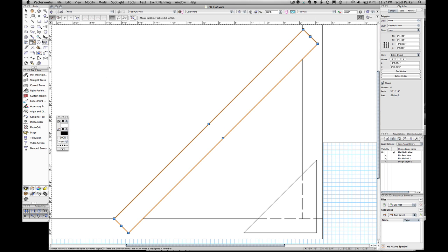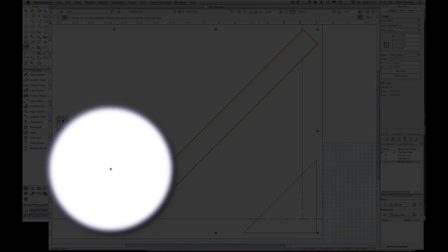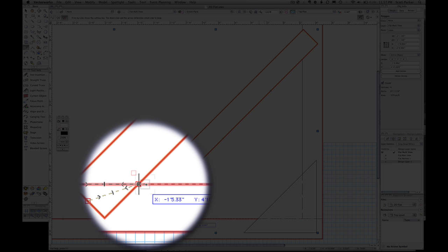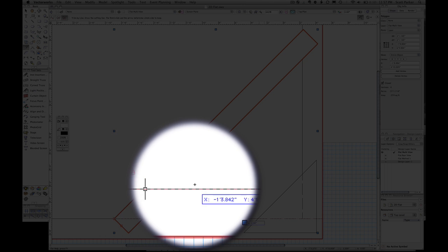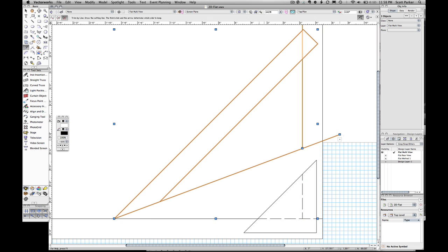So we're going to take our slice tool, or our split tool, and we're going to go down here to the corner and pull over so we can split it at this line. We're going to press the Alt or Option key because, as you can see, anywhere this line goes, everything's lighting up and being highlighted in red. Anywhere this line goes, if I click it now, it's just going to split everything in all sorts of different places and really mess us up. So I'm going to hit Control Z to undo that.